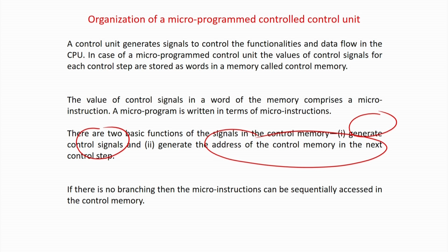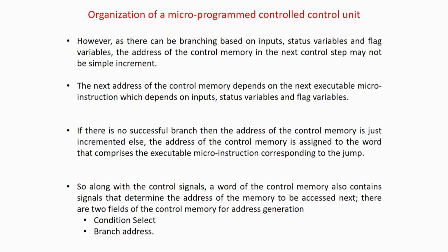So now we will see how a microprogram is organized which has to do these things. One is the control signal generation and the second is how you can do the proper sequencing. In this case, again repeating, control signal generation is very simple because you have a memory, and in all the memory bits you store the required signals which have to be made 0 and 1. Whatever I was telling you, you can read in this slide.